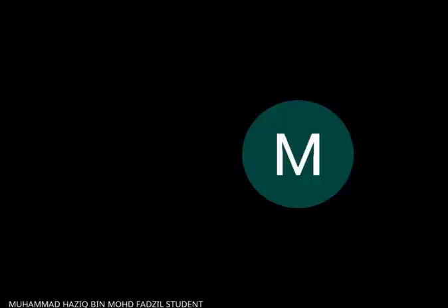We can connect two 7 segments, and the data pins A, B, C, D, E, F, G for both 7 segments can be connected to a single port. Let's say the data pins of 7 segment 1 connect to port D, and the second one also connects to port D. This means these two 7 segments share the same data pins coming from port D.